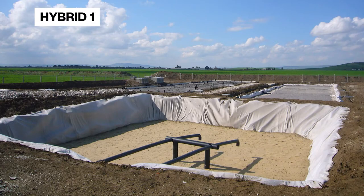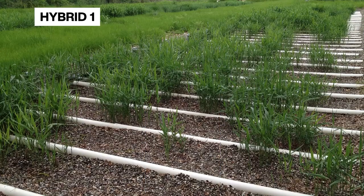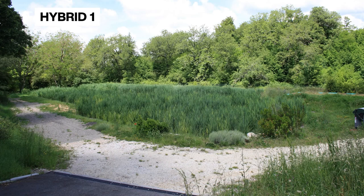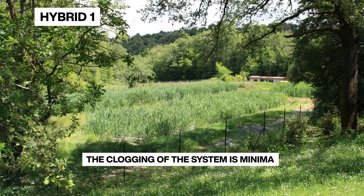The first hybrid is the most common. Vertical and horizontal subsurface flow constructed wetlands are connected so that the vertical one receives the incoming wastewater, and then its effluent is treated by the horizontal one. What is the benefit of this connection? This hybrid minimizes the risk of clogging as suspended materials are effectively removed in the vertical construction.